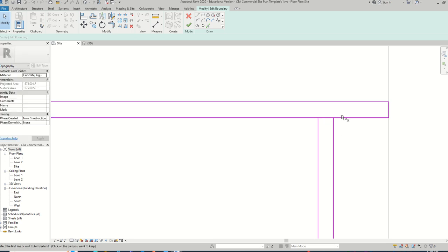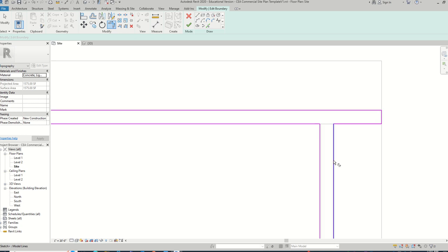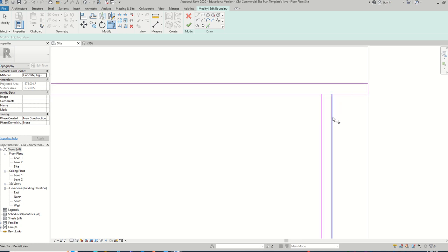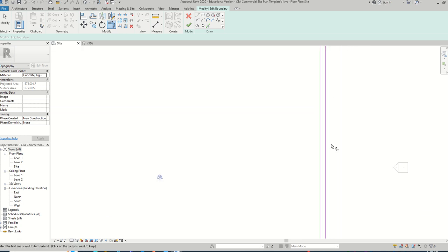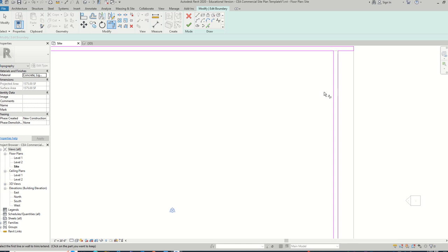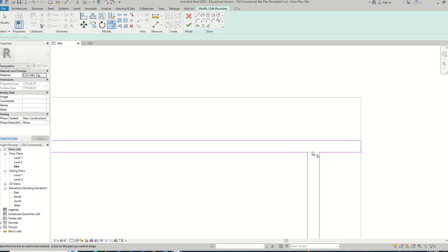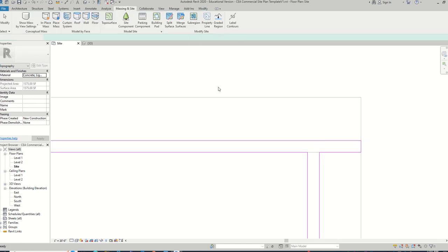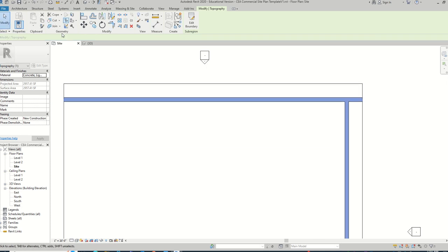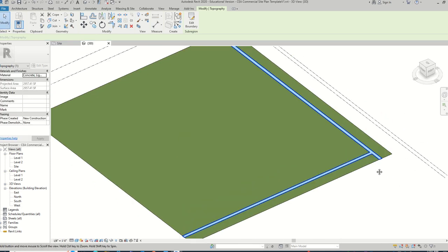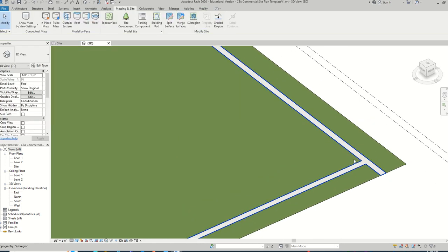Then you can use this corner tool to trim them and bring them in, have them join. From there, that should be a closed loop. Sometimes that line will just stay there like, hey, you did have a line there, and then it'll go away. Once you fix that, your concrete pathway will update, okay?